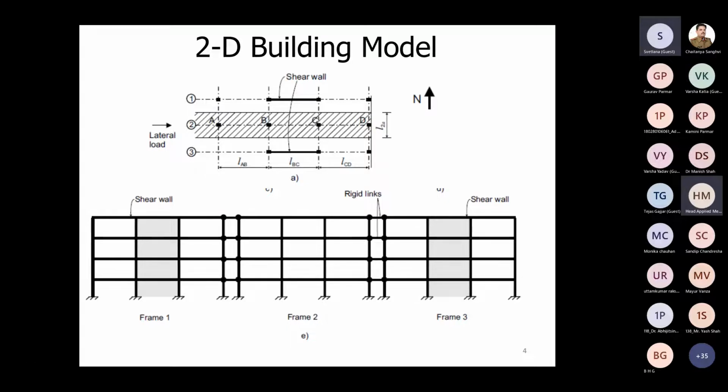So you're just taking a share of horizontal loading on each frame, sharing this horizontal loading, which we apply as just one force at the left side of the system, and then it will be shared among all these frames. So this is a very efficient and effective way of modeling.